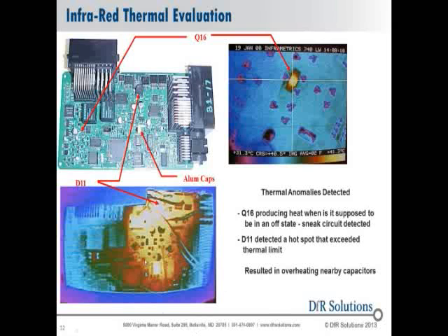Here was another situation, in the lower left-hand corner, where we had a circuit board with what we called an inadvertent design, with all these power drivers localized together that created this ring of fire situation. And unfortunately, there was a bunch of aluminum electrolytic capacitors right in the middle of that ring of fire, and aluminum electrolytic caps age very, very dramatically at accelerated temperatures. So when we saw this,